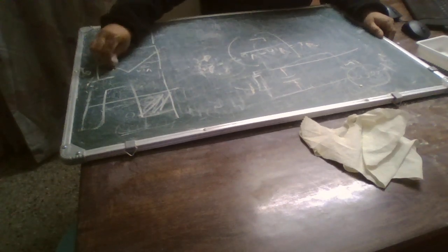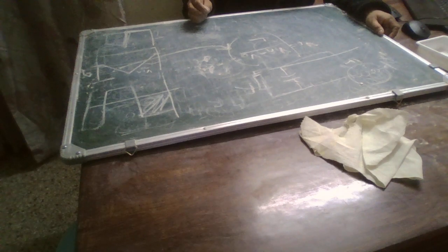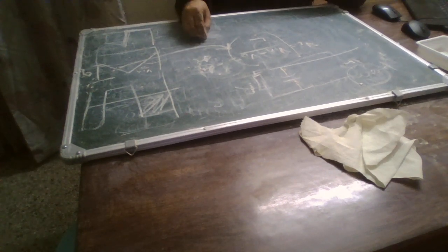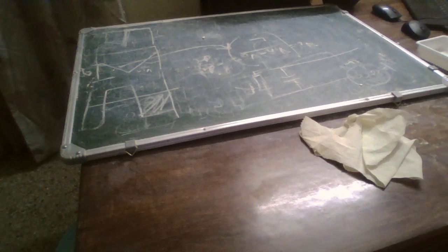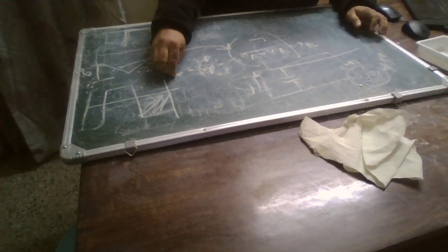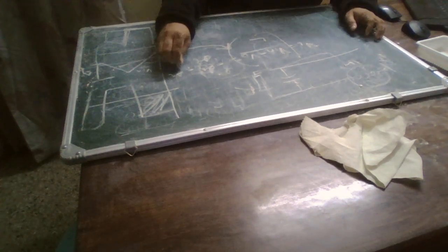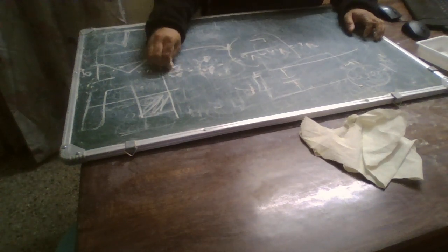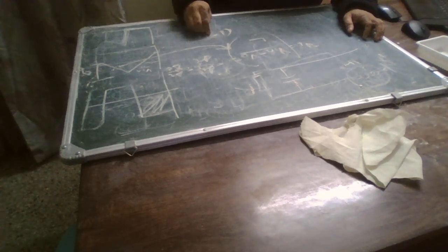That means this slope is now V input minus V output upon L. So it's going to decrease linearly with this slope. The rate of change of the inductor current is again a constant. So in di, I am going to put delta IL, and this delta IL over delta t. We know this time duration is what? 1 minus d times T. So this is the time duration for when the switch is off.